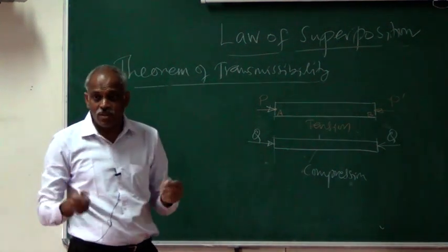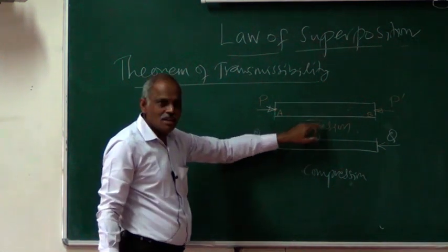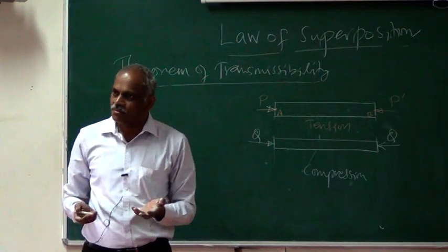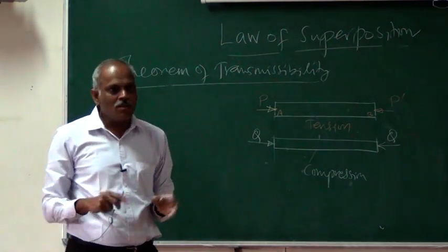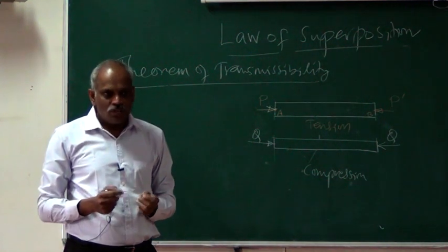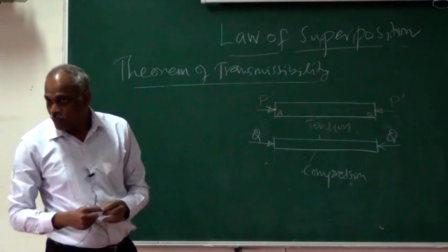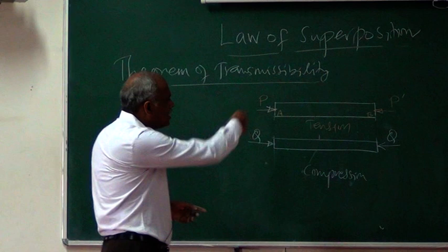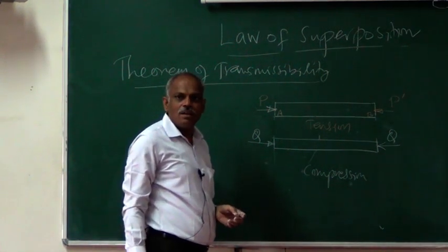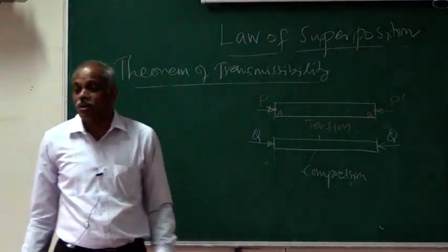But when it comes to the internal forces, what happens? Can you think of this as still in tension? No, it is in compression. So if I use the theorem of transmissibility, I have to see whether I am bothered about the internal forces. If I arbitrarily use this, then in problems involving the internal forces, this may not work.